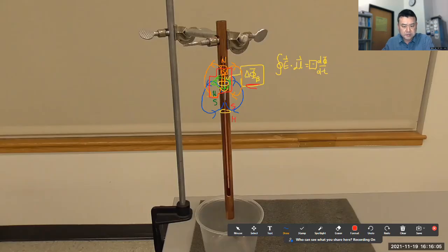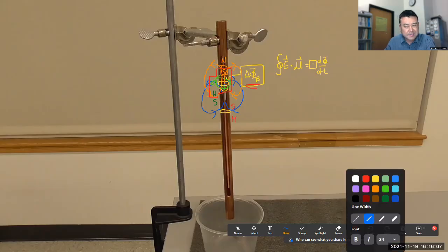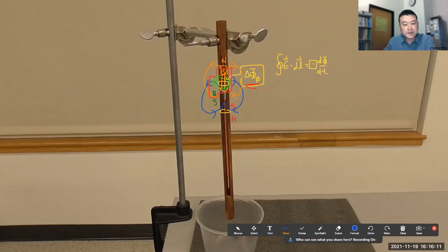And it happens for basically all the geometries that involve a moving magnet near a conducting material. So that's why we give it a special name, because it's not the specific geometry that's important, it's the effect. The effect is that it produces eddy current. We call it eddy current because if you visualize the current within the body of that conducting material, it looks like water eddies, and the directions of those eddy currents are always such that it mechanically slows down the magnet.